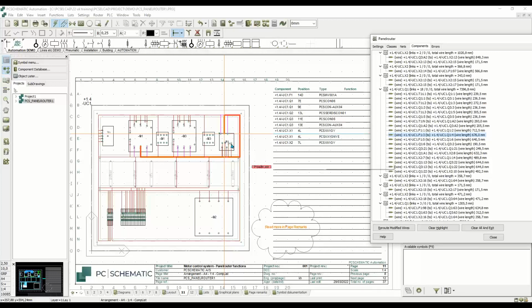And by the way, as you can see, we don't cross the wires here. So it might have been a shorter wire going from here and then down here, but we don't let the wires cross the component. So it will go up to the tray, and then it will take this route here to go down here. So that's how it uses the trays. And again, this might not be the most optimal route, but let's just leave it at that.